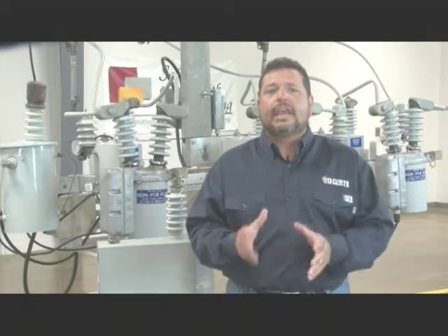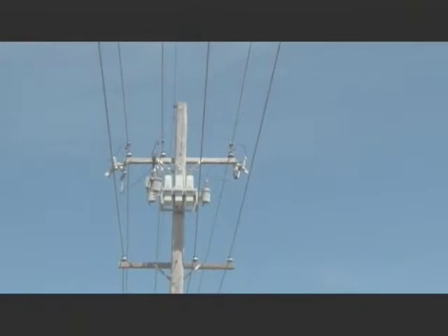If this capacitor bank had no control mechanism or oil switches, opening and closing the fuse cutouts would be the only way to energize or de-energize the bank. In that case, when the fused cutouts were closed, the capacitor bank would be a fixed bank. Because there is a danger of arcing, it is important to follow your company's guidelines when opening and closing the cutouts on a fixed capacitor bank.